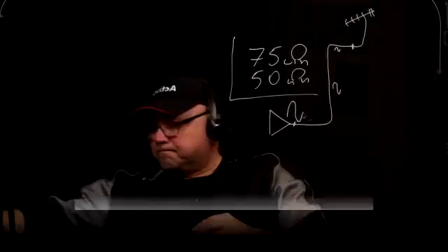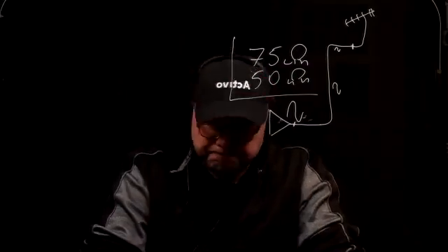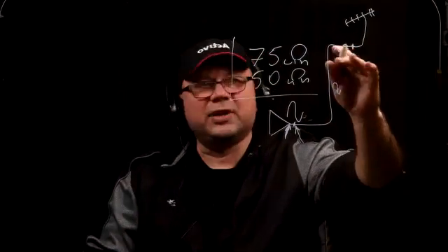here's another concept. When it comes to impedances, why do we need to know the characteristic impedance of a cable? Well, in other subjects, you're going to study something called maximum power transfer. And pay attention to this, and that's going to give you a little bit of understanding. Here's the idea of maximum power transfer: the output impedance of this amplifier has to match the characteristic impedance of the cable. And of course, it has to match the impedance of whatever receives. It could be another amplifier, another receiver, an antenna, or a television set.